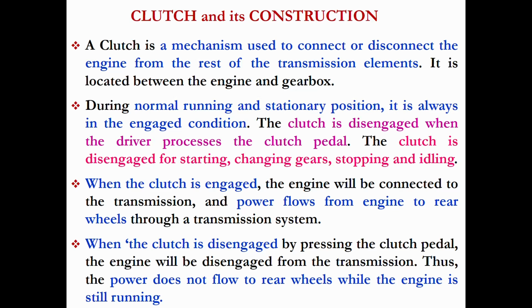Mainly, whenever power is not to be transferred from the engine to the wheel, we can press the clutch pedal so that we disengage the power transmission from the engine to the wheel. So the clutch is disengaged when the driver presses the clutch pedal. The clutch is disengaged for starting, changing gears, stopping and idling. During running condition, it must be in the normal engaged condition.